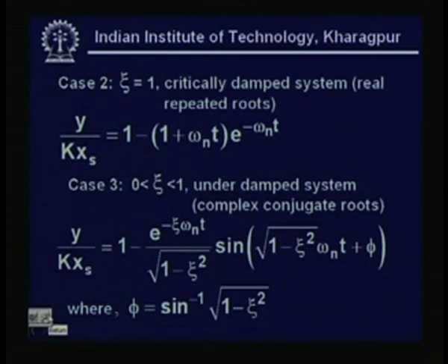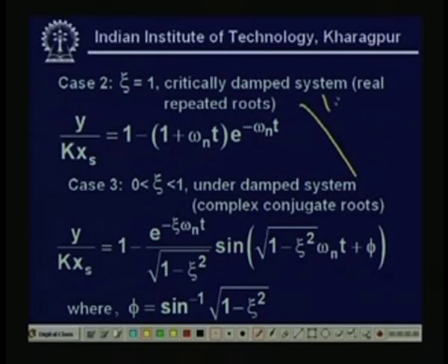Now, mostly we will try to bias our second order system as an underdamped system. If you look very carefully at analog meters, especially voltmeters, you will find that if you apply some voltage, the needle will go up, make a slight overshoot, then come back to the original position.